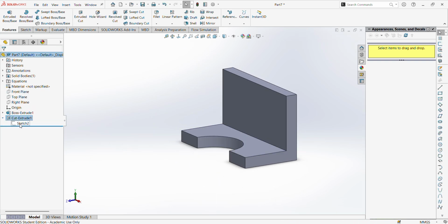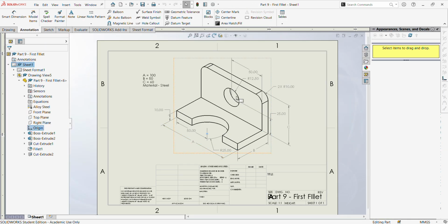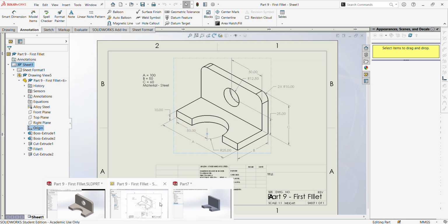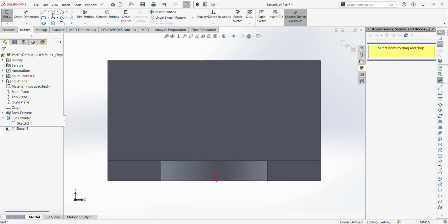Awesome. I want to double check and look at that. Okay, good. It did fully constrain it. Let's check our last cut there. Radius is 12.5, so 25 tall from this line, not the bottom, from this line. Make sure you check that out. 50 from the side, which means it's at the origin or in line with the origin. So we can actually use that to make things a little easier.